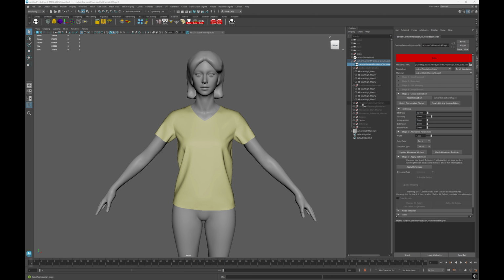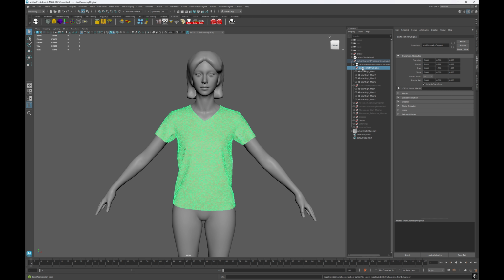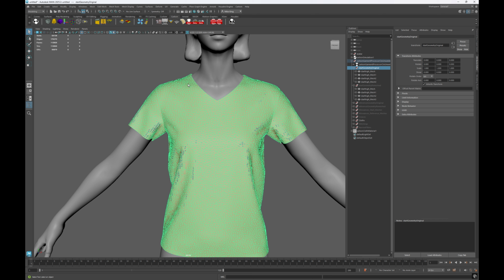So first, let's look at material properties. This garment was simulated in CLO using the knit jersey material, and also using the fitting simulation. In carbon, as part of the garment processor setup, it takes the original start mesh, which we exported as a triangle mesh, and it turns it into a quad meshed garment with very, very specific conditions, matching the armpits, for example, with the body.